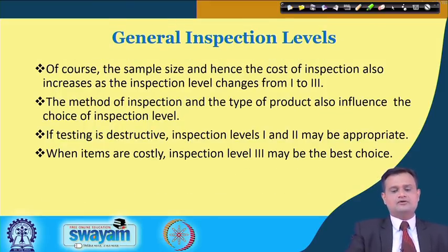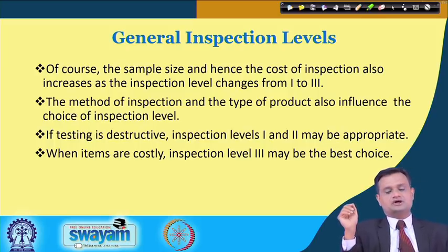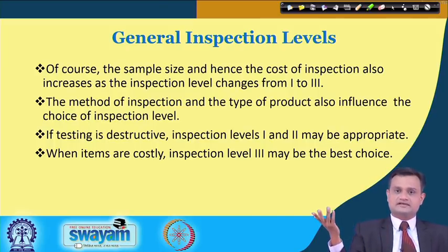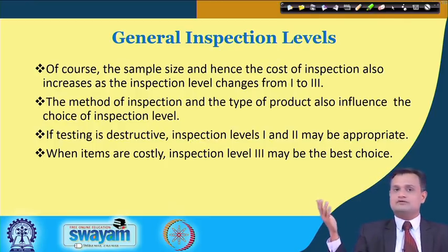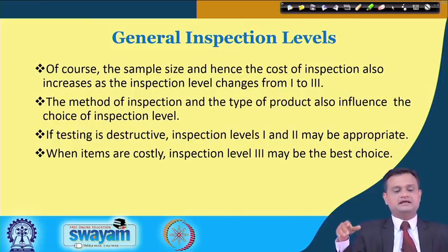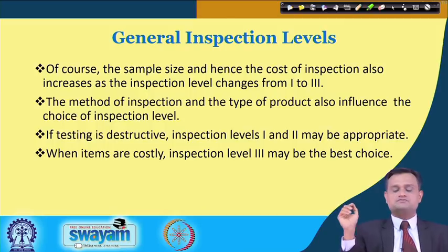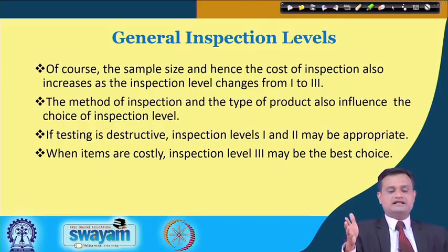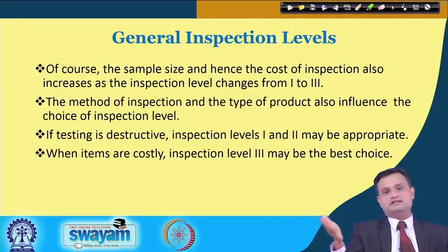With the general inspection level, the cost of inspection also increases because I am applying more and more tighter inspection. When I change from level 1 to level 3, and if testing is destructive, the recommendation is that inspection levels 1 and 2 may be appropriate, but if items are costly, then inspection level 3 may be the best choice.